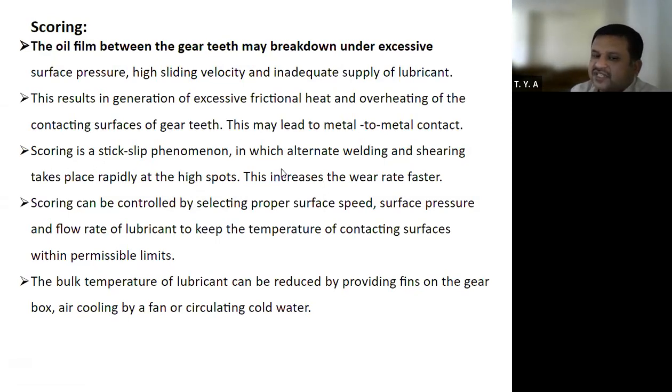Therefore, scoring is a stick slip phenomenon in which alternate welding and shearing takes place rapidly at high spots. This increases the wear rate faster. Because of this, what will happen? Heat generation is more.